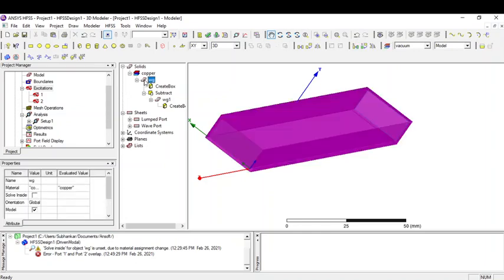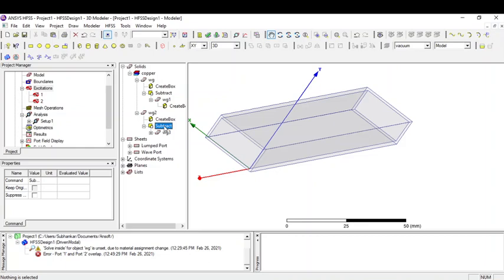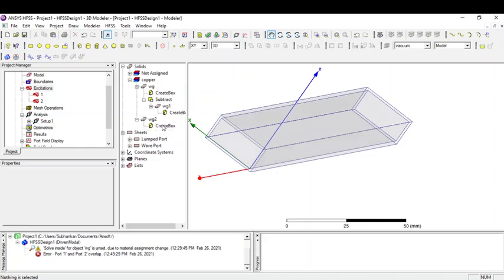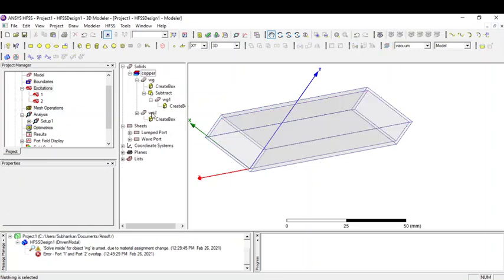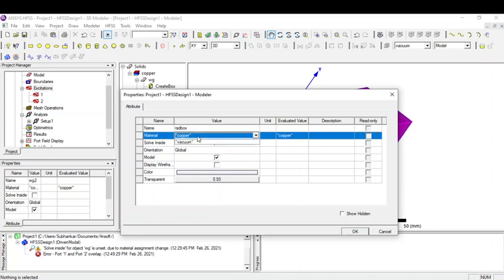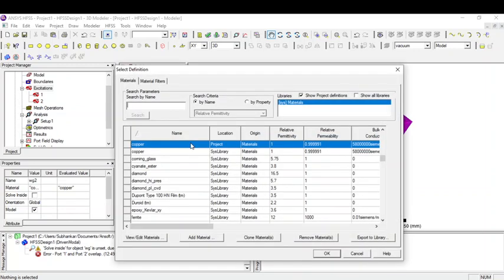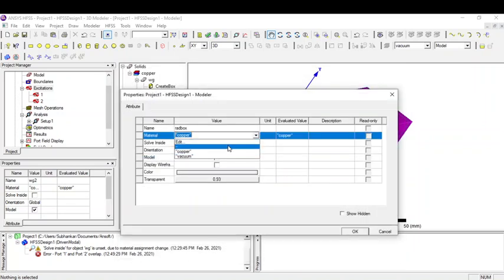So to create a radiation box, we copy this waveguide and paste it, named as WG2, and remove this subtracted portion and remove it from here also, and name this as rad box for the radiation box. It is under the material vacuum. Shown here also, vacuum.